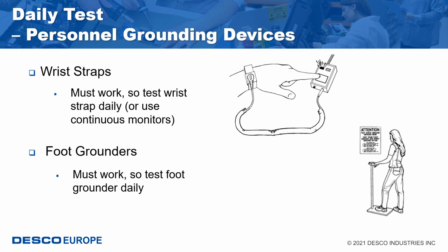Foot grounding tabs should be placed in the shoe underneath the person's foot. Foot grounders should be worn on both feet to ensure constant contact to a grounded ESD floor or floor mat. Foot grounders will not function properly if used on surfaces which are insulative, improperly grounded or highly soiled. It is also advisable that footwear be tested daily to determine if it is functioning properly with a path to ground from moisture on the person's skin through the grounding tab and via the conductive dissipative ESD footwear.